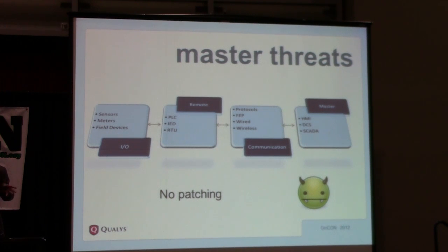Now if the Scada software vendor doesn't give you enough guidance that this patch is safe to apply or this patch is not safe to apply, as a Scada engineer or a person managing that system, what will I do? When Microsoft releases a patch, will I just go and patch the system because I want everything secure? No, my Scada vendor doesn't tell me if the patch is safe or not. So I don't want to break anything. I don't want my patch to break or stop some conveyor belt or something.